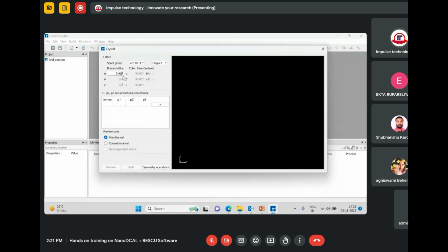Pardon, sir? Yes, tell me. Sir, actually, are these values predefined or do we have to select them? Sir, you need to select. Here you can see, first I have selected this group. Let's say we are going for the silicon crystal. Why do you take only 220, Fm-3m? Yes, because I want to create a face centered cubic structure of silicon. That's why I have selected this space group information.